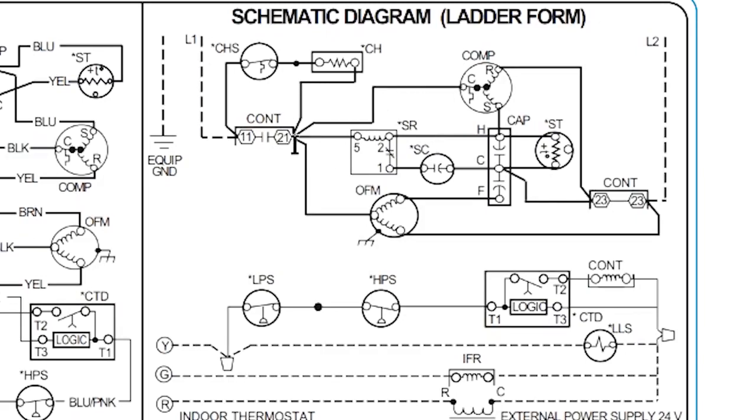Now you go through the compressor and you see the compressor common is connected to L1. L1 is connected to the compressor common through the compressor contactor. The only way that this compressor can come on is if this switch goes from normally open to energized and closed, so the slash. So it's got to get the slash across it, the path across the switch, for the electrons to travel through and hit the compressor.